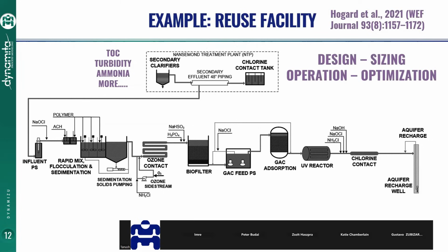chemical addition, polymer addition. Then it goes through an ozone contactor into their biofiltration where they remove TOC. Then it goes through a GAC, which is granular activated carbon, UV, and then it's ready for aquifer discharge.